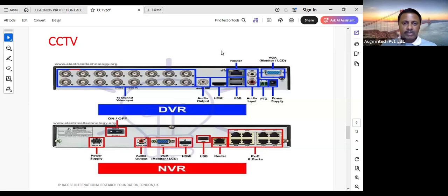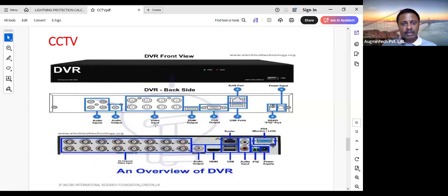Yeah, and that option is also available, but still, Mr. Tony, a minimum power supply is required because Ethernet cables are not directly supplying the power actually. It's completely data or voice only. Nowadays special types of cameras are also available, with batteries and other things. But still, whenever we procure the battery, we have to confirm what power supply is required. But as usual, both power supplies would be required for your cameras as well as for this controller also.